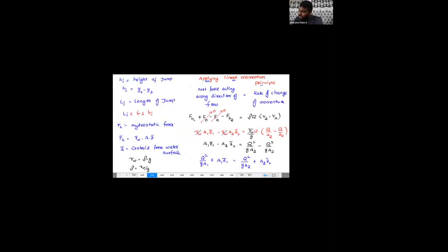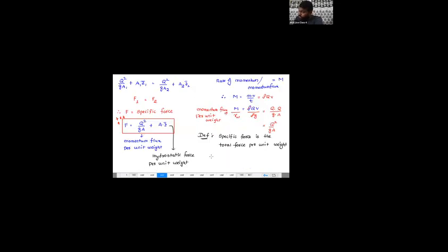See, this is not a moment of the hydrostatic force. Please keep that in your mind. For a rectangle, a lot of students are asking, what is the hydrostatic force? Gamma W into A into Z bar. Here is the water level, and the centroid is just below the free water surface.